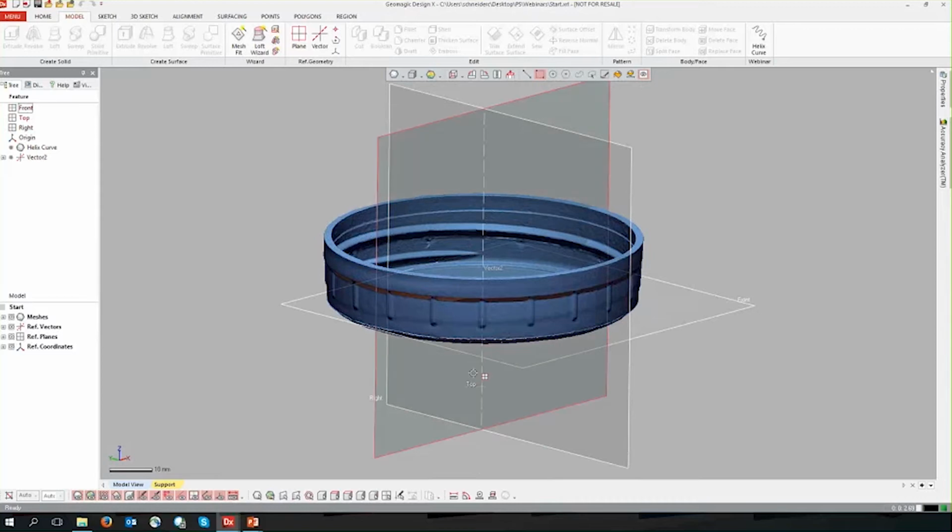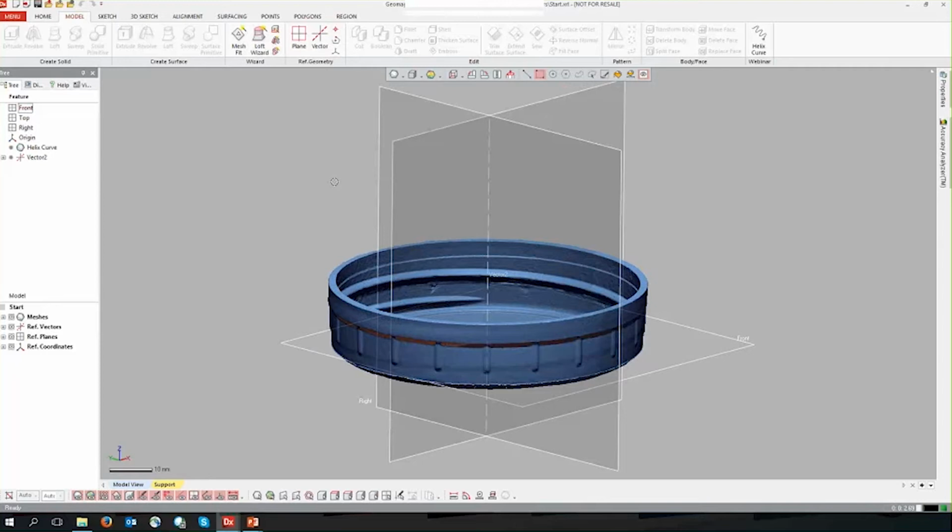There's one other thing we need to start our helix, and that is the starting point. The helix can have a reference point, just a reference geometry to start our point. But another trick to use this tool for is to get a sketch point to be your starting point. As parts wear and are used, usually the geometry you're modeling isn't there. So instead of having to find a way to move a reference point from the scan itself to someplace in space, it's easy to just generate a 2D sketch and generate that point there.